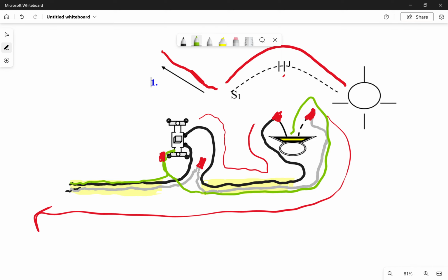Some lights would have a ground wire coming off the light. Some would have a grounding screw. The lights that we're using are actually very, very inexpensive lights, and they don't have a grounding screw. So we're going to just leave it dangling inside of our box, but we will touch on it. We will talk about it when you guys do that, as to where that's okay and where that's not okay.